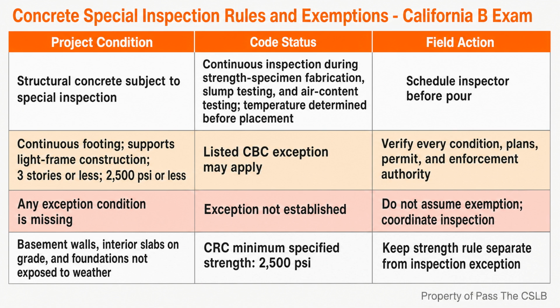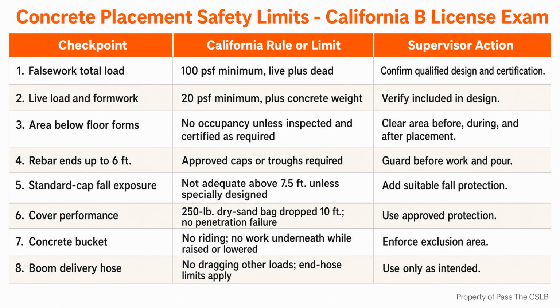Employees cannot occupy areas underneath building floor form installations before, during, or after concrete placement unless the forms have been inspected and certified as required. That restriction matters because the load path is active above them. The concrete, forms, workers, equipment, and localized placement loads all act on the supporting system.